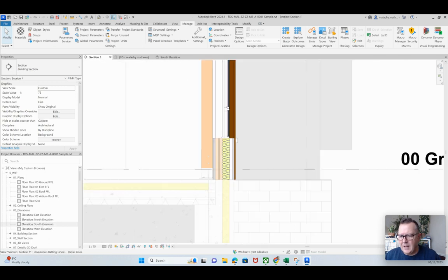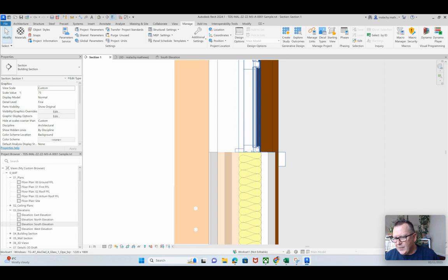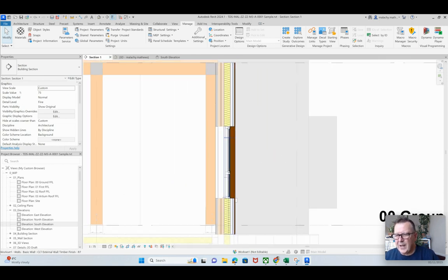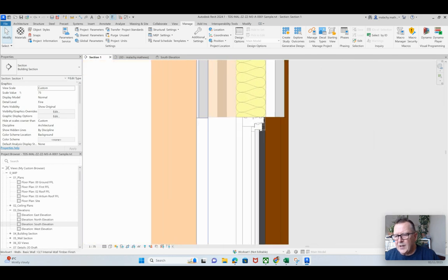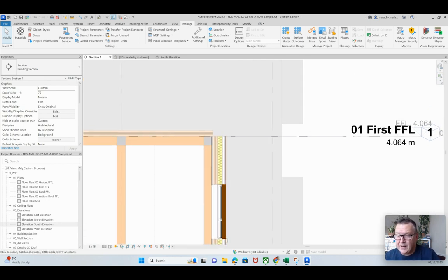Last thing, so I got that area roughly sorted out. You can see I'm going to have to put in a sill. It does show a sill on this particular family. It's not a great one, to be honest with you. I might extrude in a window board there just to cover that. And I might extrude out plaster just to cover that. We can cover those in the 1:20, 1:10 details that you're doing later.